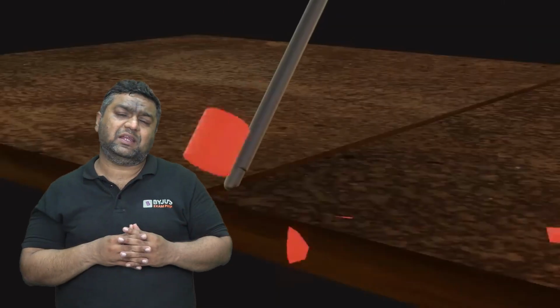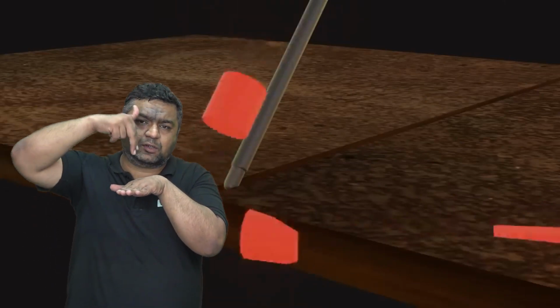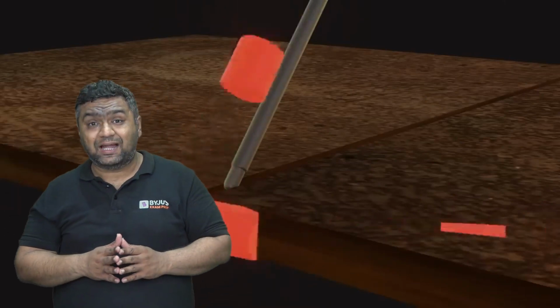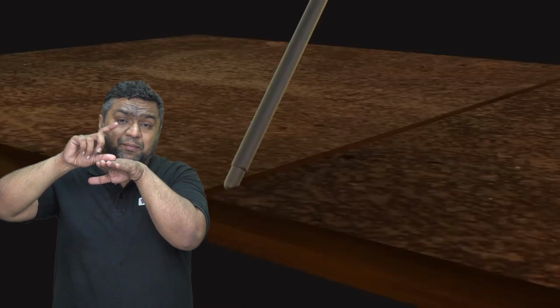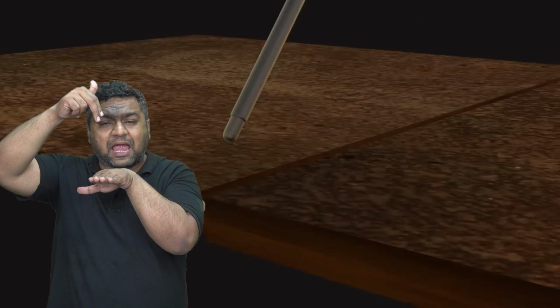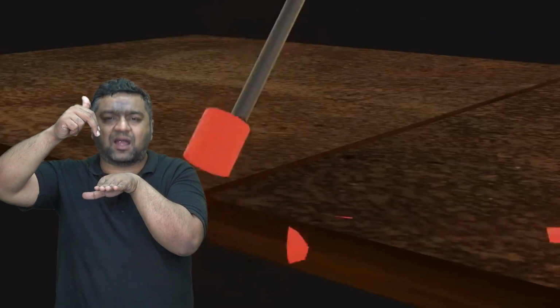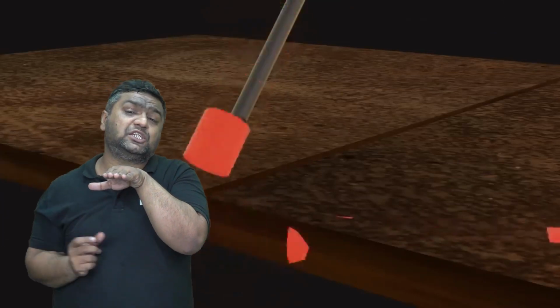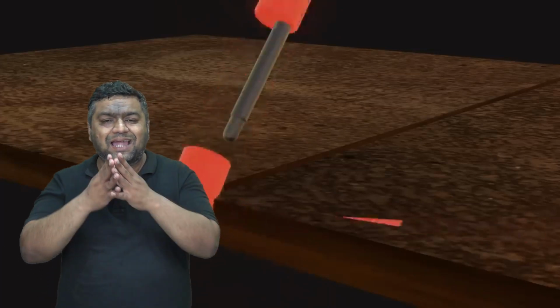Now my dear, whenever the electrode is coming towards the workpiece, you know that only when this distance becomes critical does welding start. If you have more gap between them, welding will not even start, because the voltage is not enough to start the welding. That condition is said to be open circuit voltage.